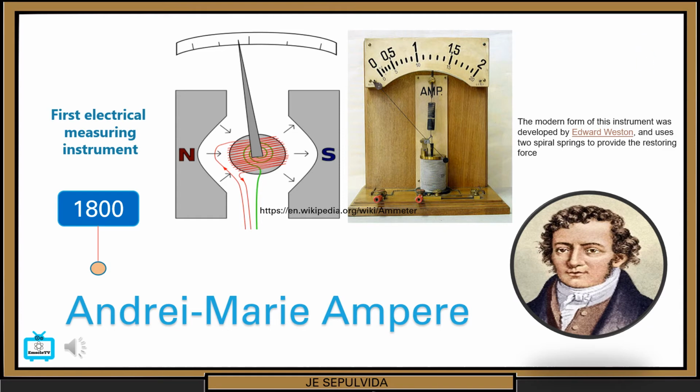This ampere, called the International Ampere, was not the ampere that scientists use today. Instead, this ampere was realized, transformed from definition into practical reality, with a device called a silver voltameter. This device contained electrodes with positive, anode, and negative, cathode, terminals. The anode was suspended in a solution of silver nitrate. When current passed through the device, silver would accumulate on the cathode. Researchers would then determine the mass of the cathode before and after. The amount of silver on the cathode indicated how much current had passed through the device.